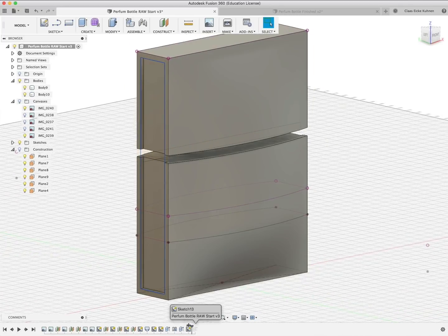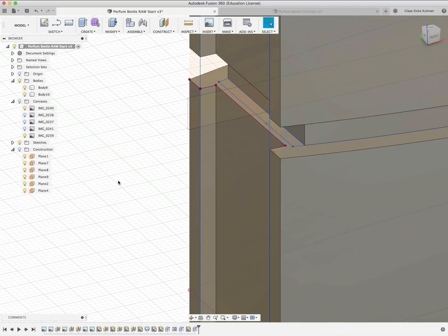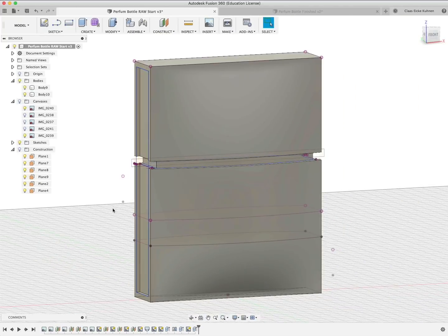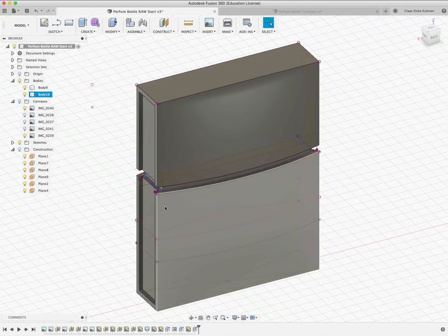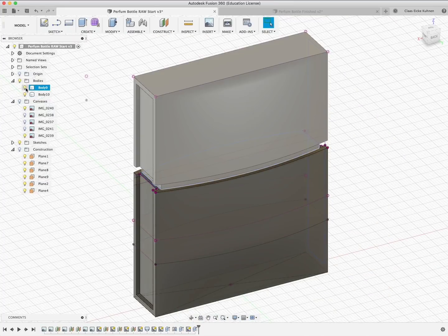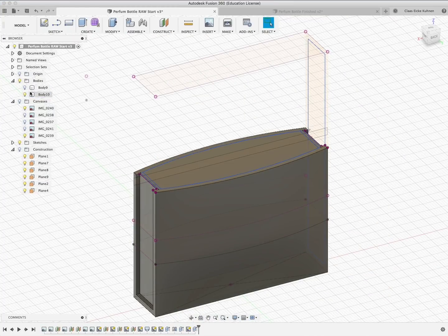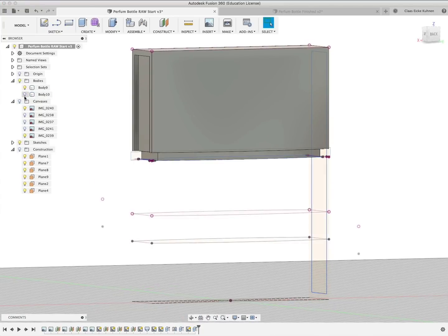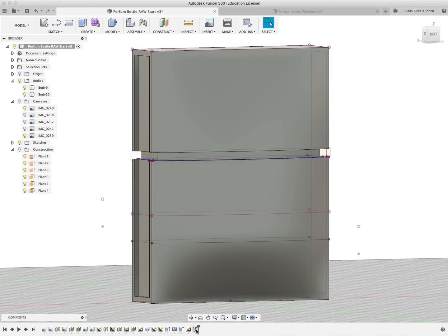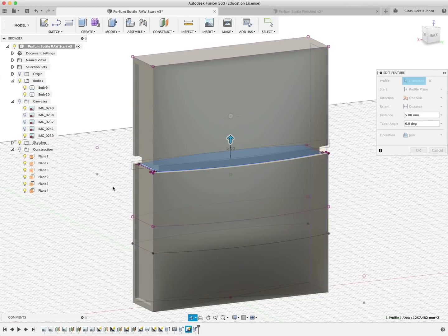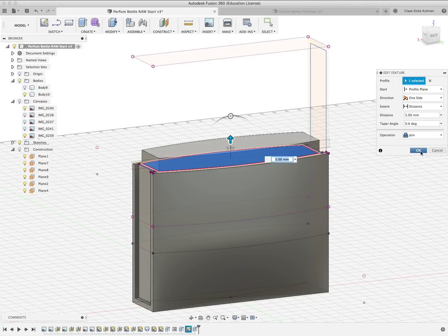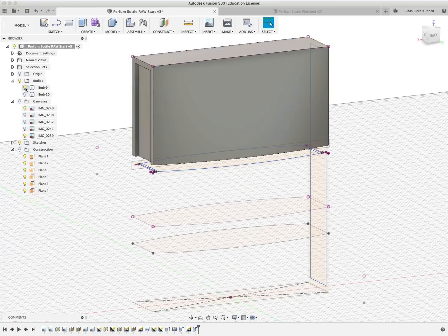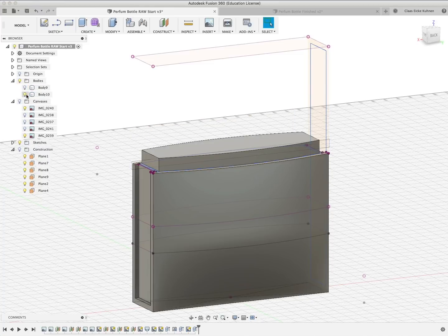Cut this out. Very nice. Go to the sketch and let's see if everything worked out. Okay, good. So no problems arise. So the top part, oh, where is this feature? We actually did that extrusion. That's interesting. It joined it to them, and so I have to edit this. Fusion got a little bit confused already. Here only join this to this body. Correct. Okay, so there you saw there was a tiny mistake.